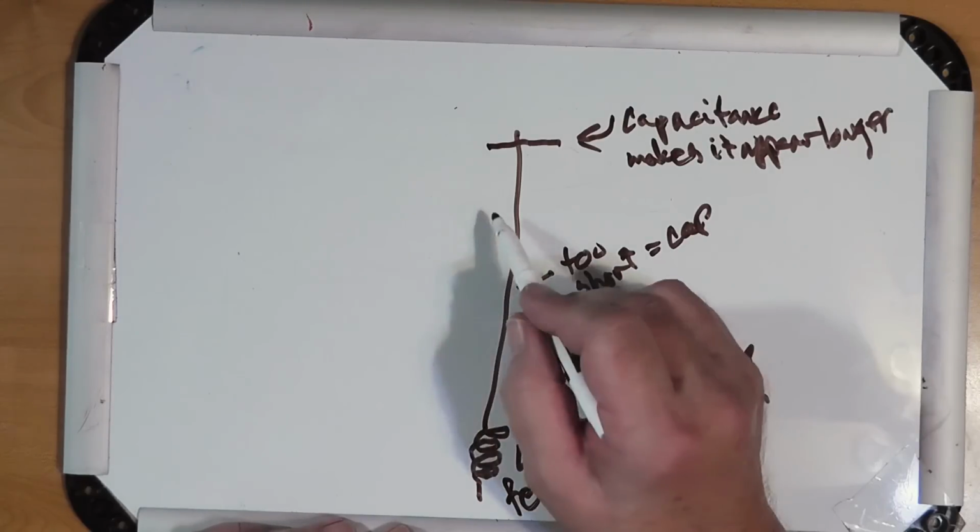You'd say that part radiates, and it does. But the thing is, what we are talking about in RF terms is a system, and this is the whole system here. Okay, and that system will resonate at a certain frequency. And because it is resonant at that frequency, it will radiate.